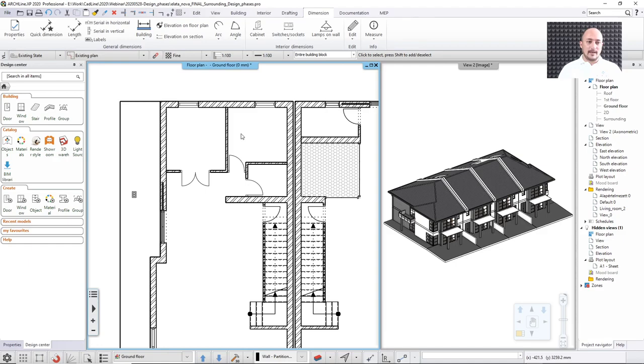But if it is anchored to an item which is in one design phase, and another anchor point is to an item which is in another design phase, then the software will continuously represent it, because it will not solve that situation automatically. There is no automatic solution to such a situation. So you need to make sure that you create dimensions to clear situations. Other than that, you will see that it will sometimes appear and sometimes not, which is, I think, quite logical.